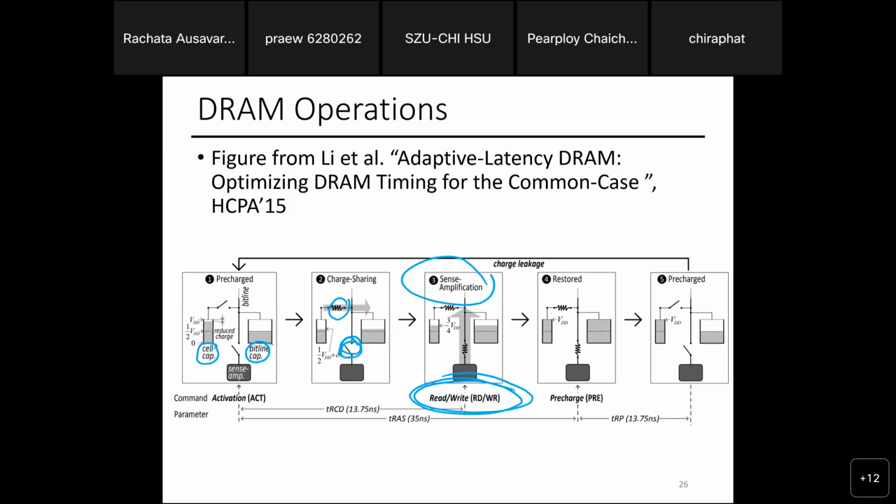So see how from here I connect everything. I now disconnect everything. That whole circuit will have a reference voltage, which means that I will supply the power so that it always goes back to this value. That value is 1/2. So the bit line capacitor will always go back to 1/2. That is when you finish pre-charging, because then you can go to a different row, which has a different capacitor, and close them so they share the charge again and can read the next row.